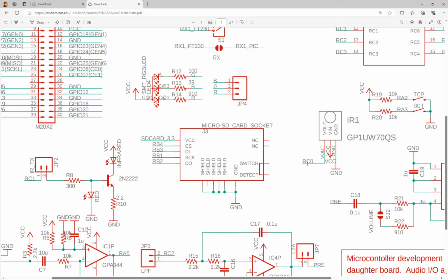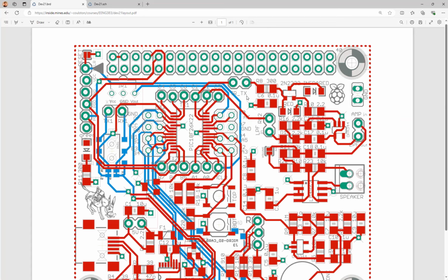So RC0 will be what? Input. It will be input to the microcontroller. RC0, keep that in mind, all right? So this is the output of the microcontroller, because the microcontroller outputs the signal to drive it, and then the signal is received and decoded, and we put the signal to RC0, and it will be read by the PIC through the RC0 pin. Make sense? That's everything about the hot wire.